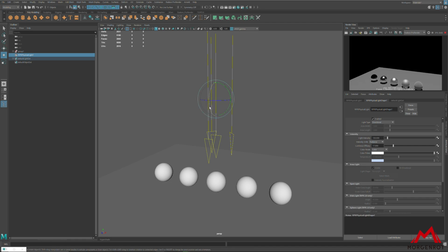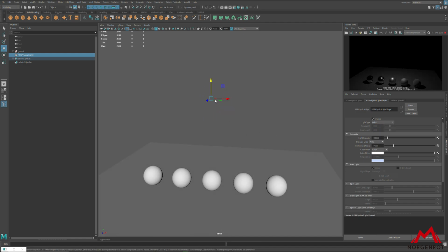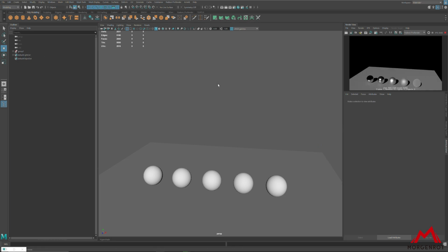By using the Rotate tool, you can change the position of the sun. Intensity and shadow softness angle are the only parts that can be adjusted for this lighting. For the point light, you can adjust the intensity and the color. You can cast the light from one part of the area. That will be all for the 4 basic lightings.